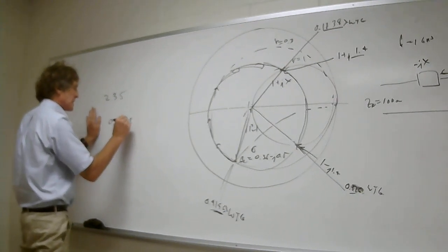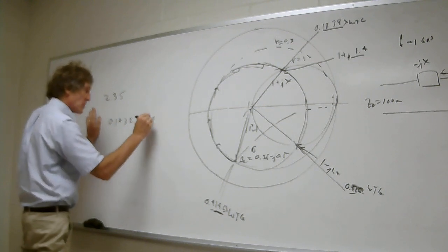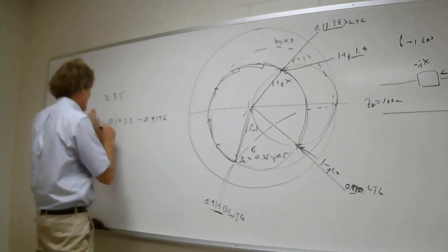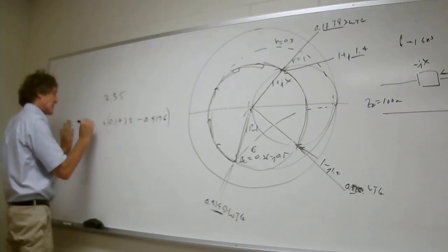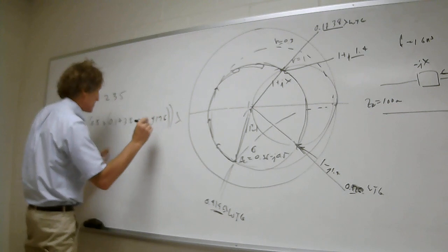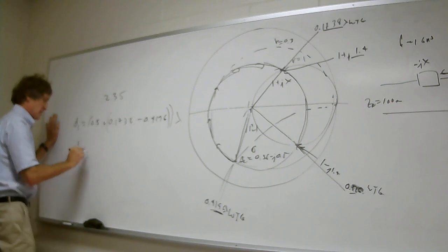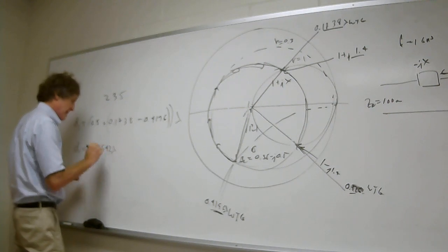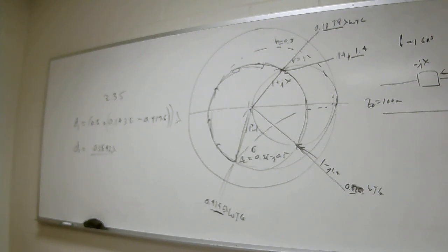0.1738, right? That's the mile marker we stopped at. We subtract this from it, 0.419. Something like that. And you'll notice it's negative, so we have to add half a wavelength. And this is how many wavelengths we're going to move. I'll call it D1. What is that? 0.2542 lambda. So over here, that's how far we move.